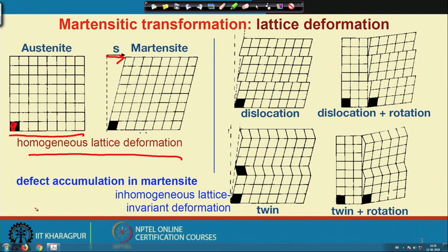However, if we have a polycrystalline grain, and this grain is austenite and it is going to transform into martensite, then it has to be accommodated within that region, and we need to introduce some defect inside it, so that the lattice strain or invariant strain is accommodated. For that, this same amount of shear vector we can split into local domains in this way by introducing some dislocation.